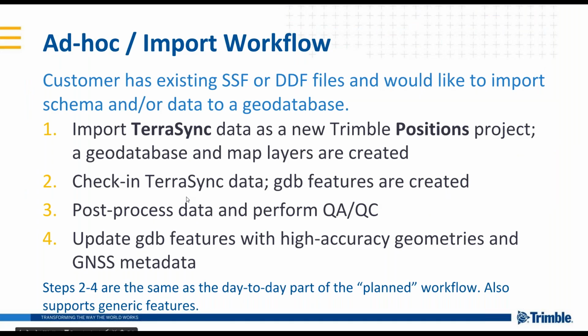So the second workflow that I want to talk about is kind of this ad hoc or import workflow. So this would be a case where you have an existing SSF or DDF file. This is data you've already collected. Maybe it includes generic features. It's based on your own data dictionaries you've already used, or it is a data dictionary you've already set up, and you'd like to import that very quickly and easily into a geodatabase, get those sessions in, work with them.